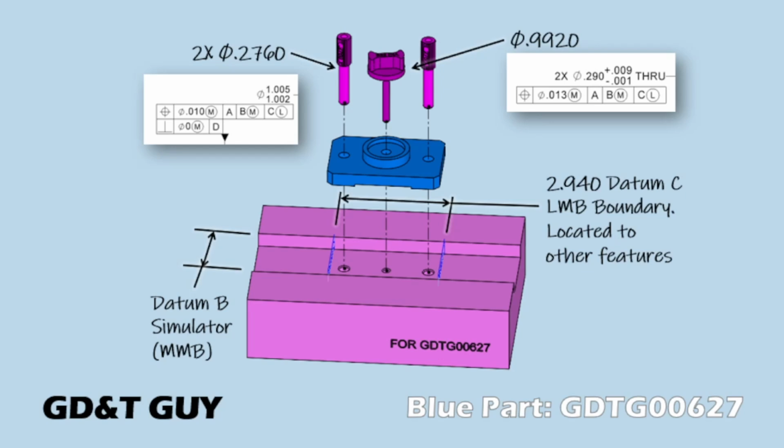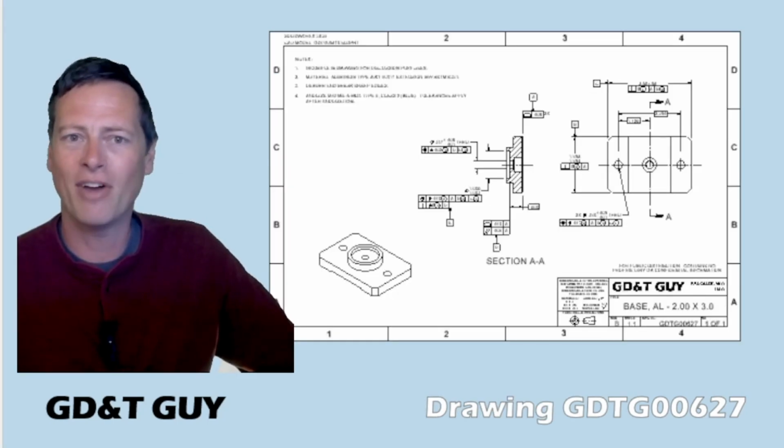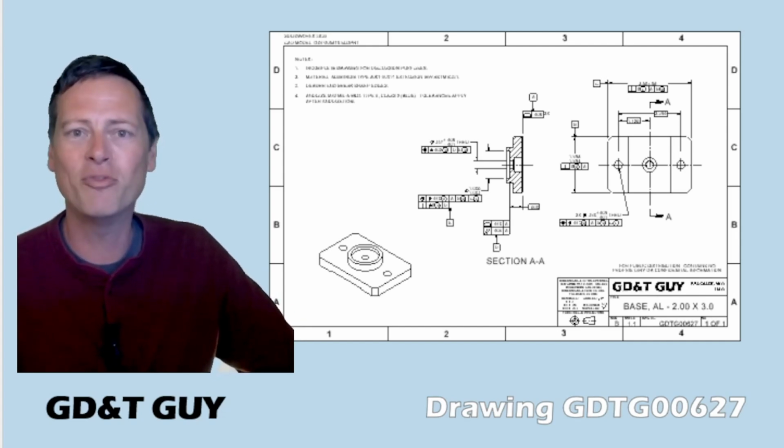That's very circle L. Be there. Preserve material. It's the opposite of how, like, circle M is all about clearance. Circle M is all about getting out of the way. Don't be there. Remove material.